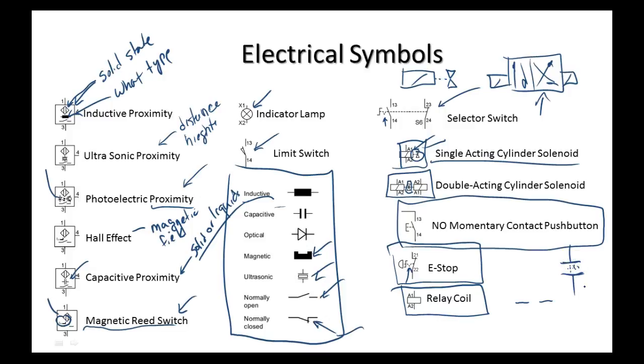So you got to put AC on it. The capacitive sensor and the inductive sensor work off AC, so there's an oscillator circuit. Now what determines the amount of capacitance is what you put in the center of those 2 plates, and we call it the dielectric constant. It's all in reference to the dielectric constant of a vacuum. So a vacuum would have a dielectric constant of 1.